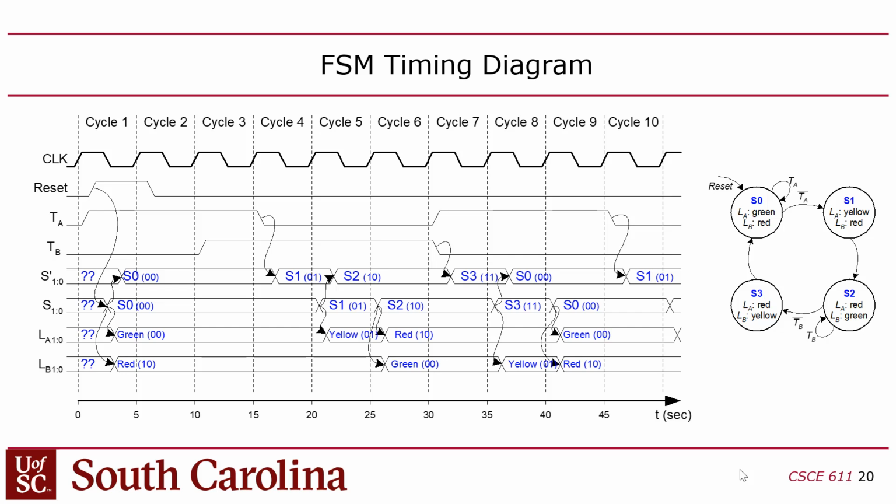But when do these change, by the way? Traffic sensors, you could tell, are changing on the rising edge. See that? Rising edge changes. This guy changes on the rising edge, right? Now, this diagram also is putting a little logic delay in there, too. You see that the dotted lines represent the rising clock edge, but notice that stuff is changing to the right of the dotted lines because they're trying to simulate a little logic delay. If this were in ModelSim or Questa-Sim, you wouldn't see that logic delay. It would be invisible because by default, there's no logic delay in ModelSim. Everything's happening instantaneously on the edge, right?